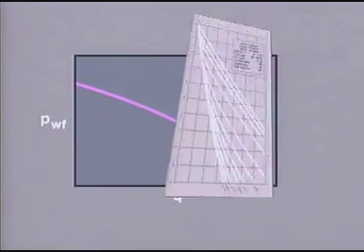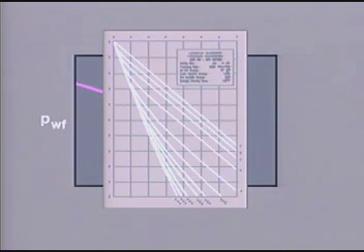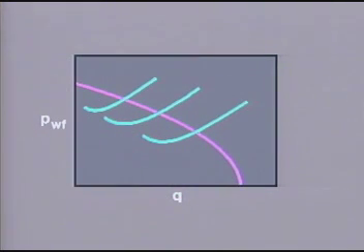Using any of a number of vertical multiphase flow correlations, which relate pressure drop up the tubing to variables such as tubing size, water cut, gas-liquid ratio, and fluid properties, we can calculate various tubing performance curves. These curves allow us to graphically determine the flow rate for our system for any combination of parameters.